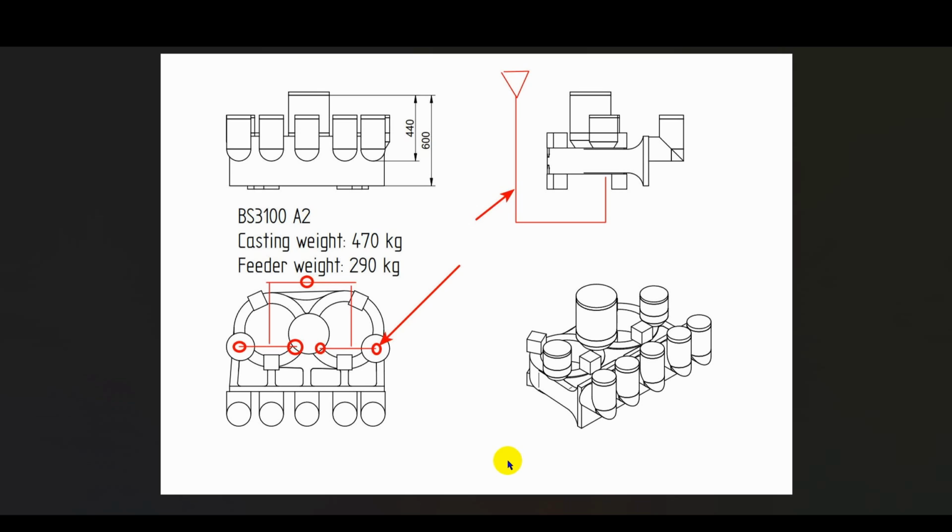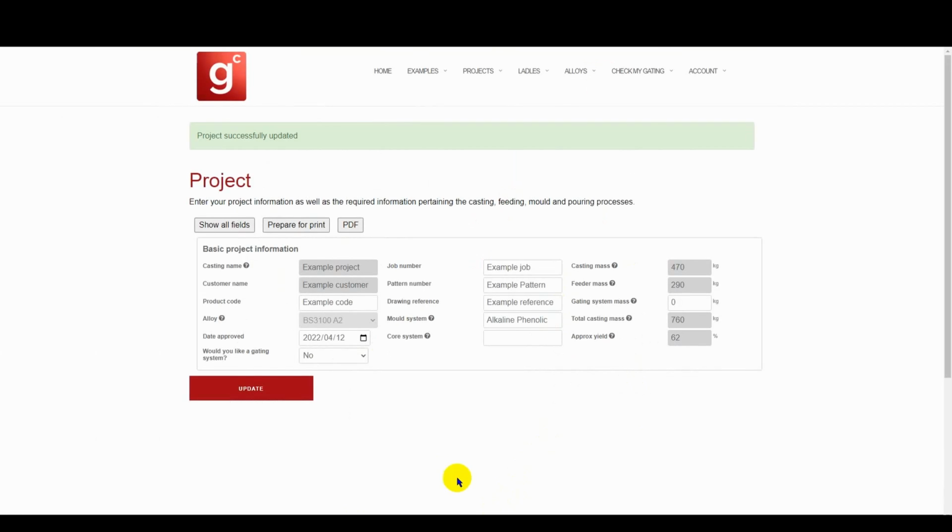our efficiency and quality. The total mold height is 600 mm or 60 cm, while the distance between the parting line and the top of the mold is 44 cm or 440 mm. The feeders have already been optimized in a simulation software program like Magmasoft. We are now ready to determine a good starting point for our runner design.